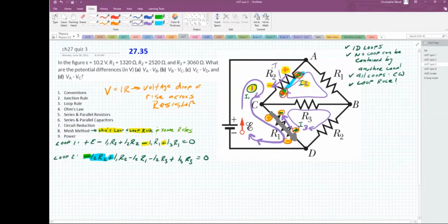So this is I1, this is I2. And you can see I'm drawing it right there, very up close. I2 is going from positive to negative. So that's a drop. But over here, I have this negative to a positive. So that's why this is counted as a rise. So this is a drop, and this is a rise. And the way I always think of them, they offset. I2 and I1 offset each other. That's why that's negative, that's positive. Okay, so let's just finish this. Done with that resistor. Let me keep the clutter to a minimum.